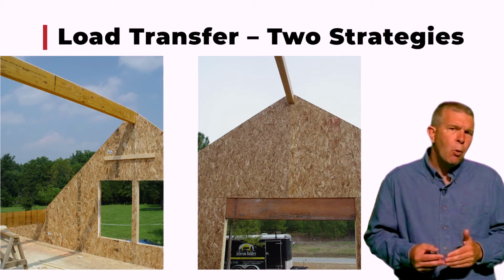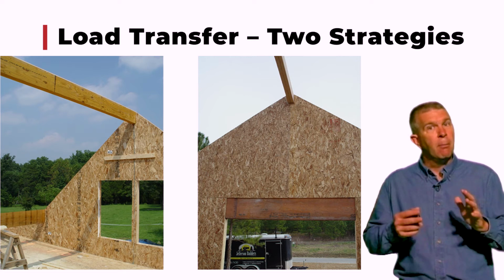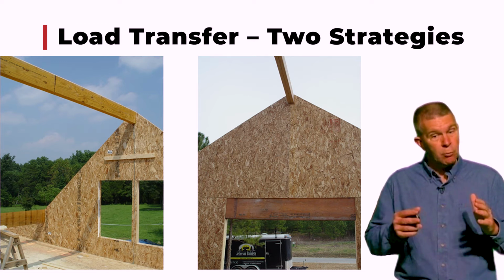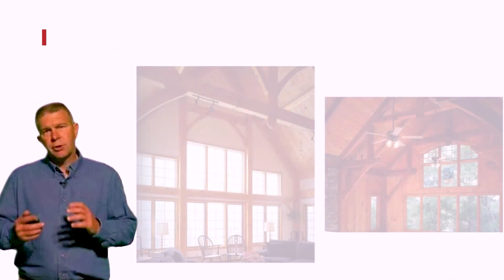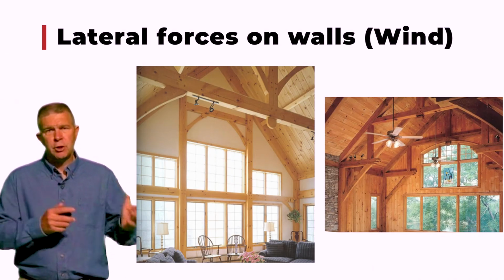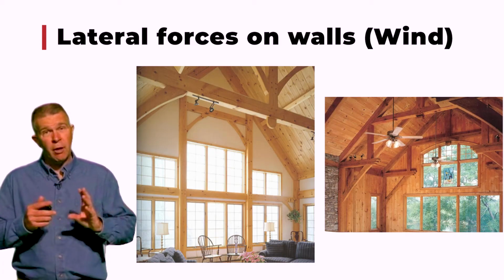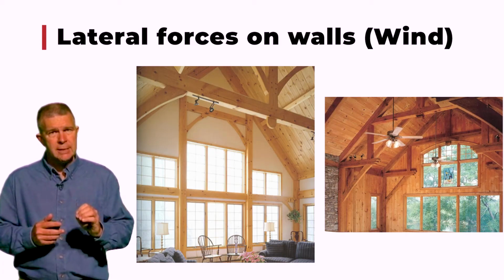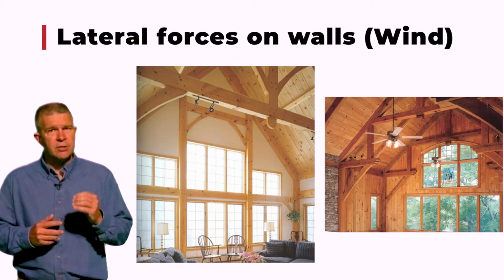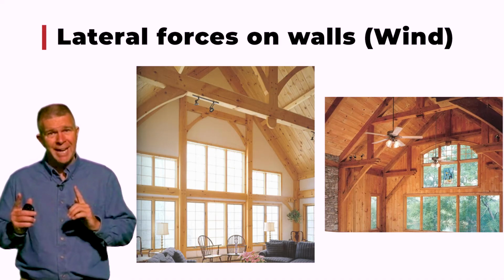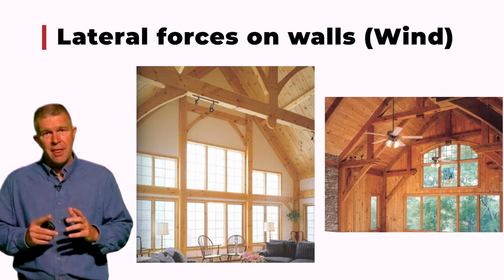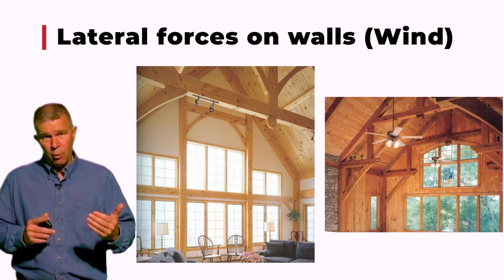So point loads are something that you have to be mindful of as to how you're going to get that load down through your wall system and around and into the foundation. While we're still talking about walls, and we've put a bunch of windows and doors, we've dealt with headers, we've dealt with point loads, the one thing that the designer needs to pay particular attention to is the lateral force that is the wind. These two photos show good and bad examples of designs that handle the wind force.